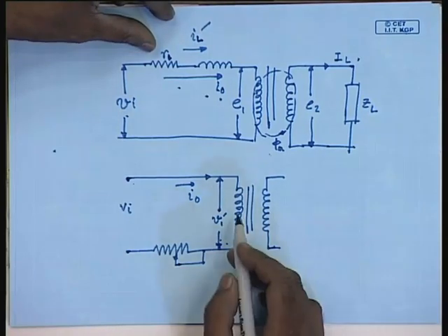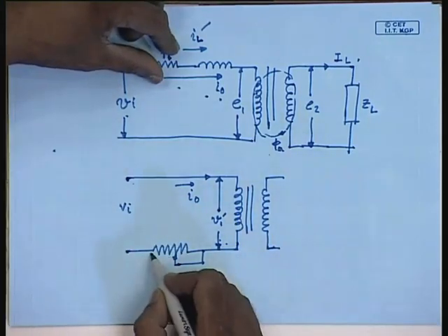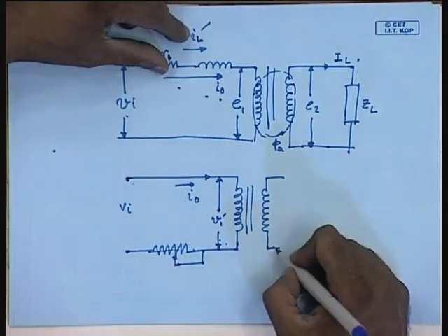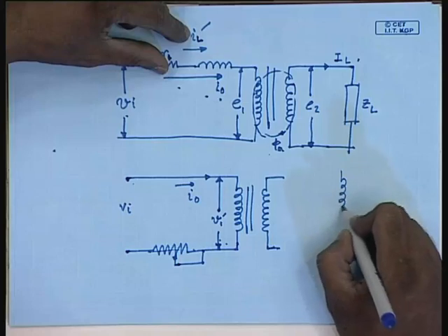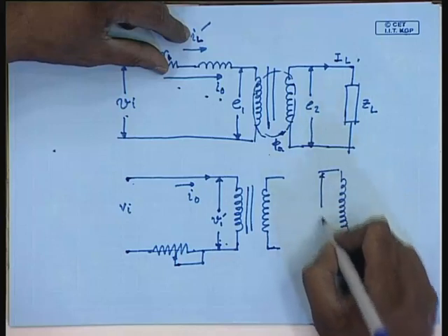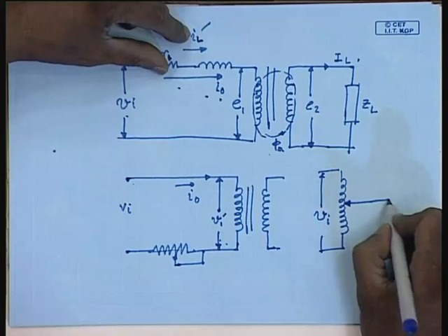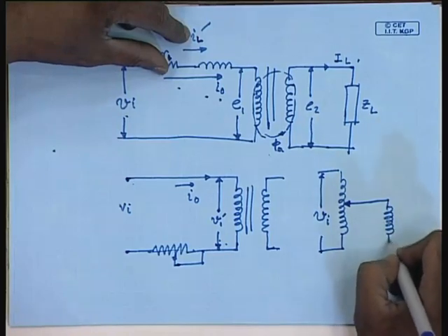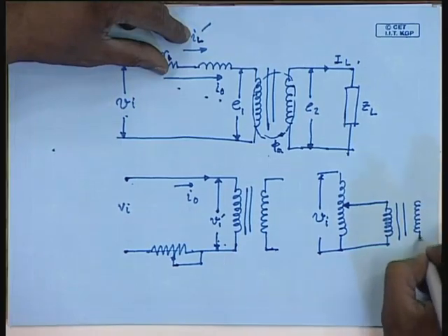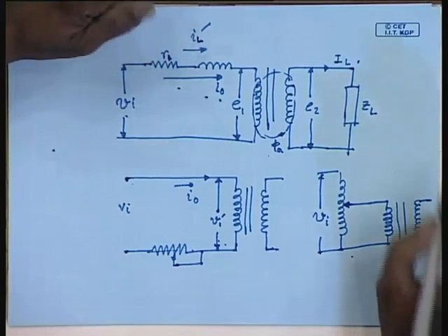Hence, for doing a no load test under such a situation, it will be preferable, instead of using a resistance to drop the voltage, to use an auto transformer, variac, in order to reduce the voltage to the desired level, because the induced voltage in the auto transformer will be almost sinusoidal.